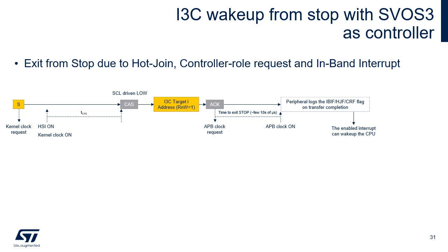issue an ENTASx CCC, generally with x equals 0, 1, 2, or 3, to inform targets that the I3C controller is not expected to exit from idle state, nor to communicate on the I3C bus, before an interval of, respectively, 1 microsecond, 100 microseconds, 2 milliseconds, or 50 milliseconds has elapsed. This delay defines the TCAS delay for the controller to set the SCL bus clock low and running after a start condition. More specifically, for a stop mode, the CCC must be restricted to an ENTASx with the value x equals 1, 2, or 3.